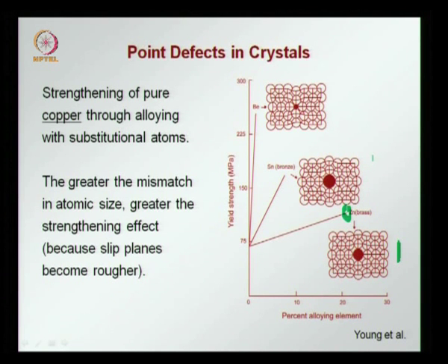Now in the case of bronze, where you have tin being introduced, the tin atom is larger than the copper atom and also the zinc atom. So when we substitute one of the copper atoms with the tin atom, there is a higher distortion of the lattice around. You can see that there is more distortion here, so more strain is introduced, and this has two consequences.